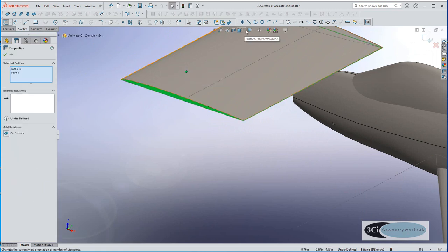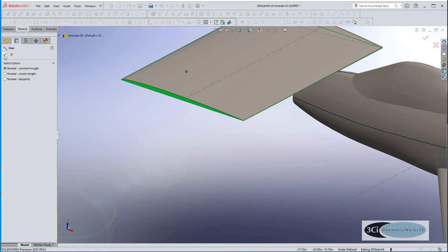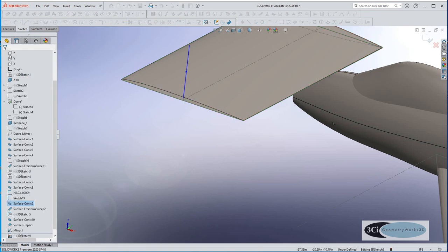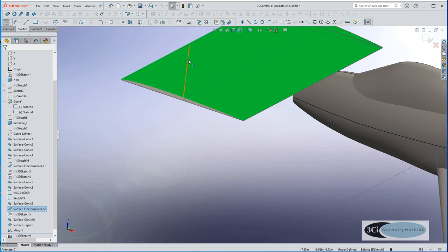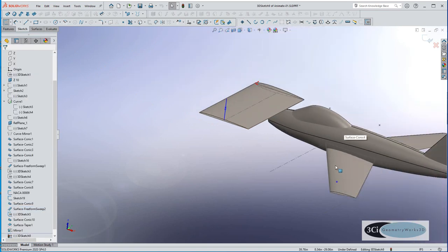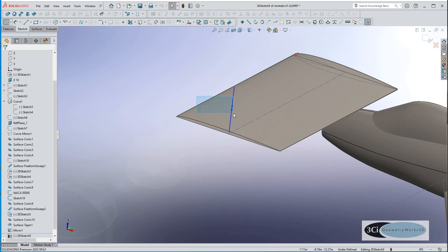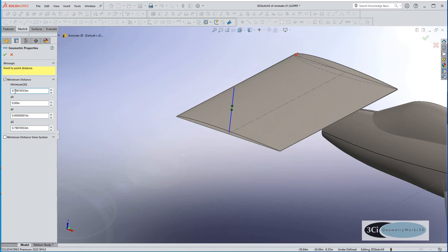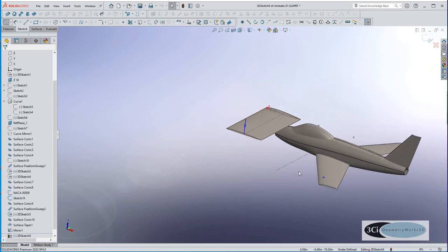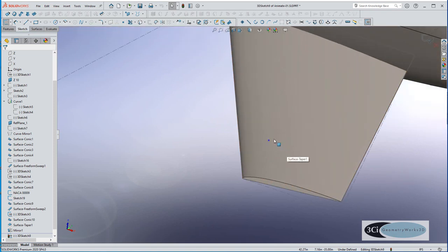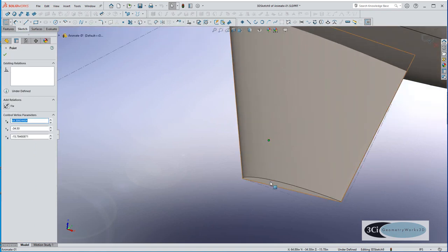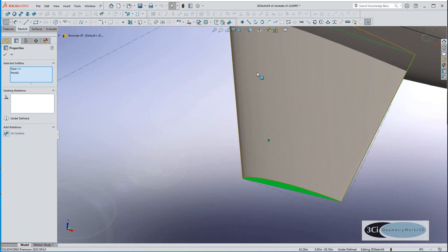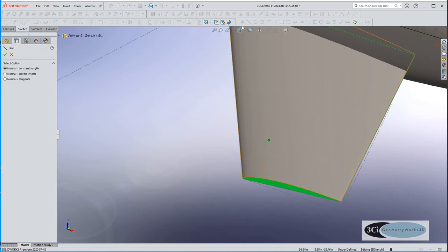We'll create a normal line, which represents a normal vector. So create a line, and then we'll test to see how far away the surface is over that point. We'll do a measure, capture the measure, Control C. Then we go to the destination reference surface, where we have already calculated where the point is.